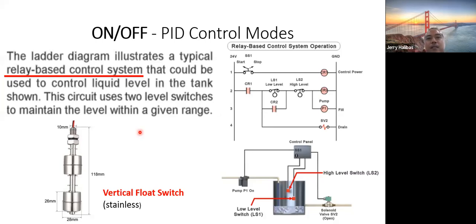The first difference is that electronics is faster. The relay system is much slower. But if speed is not the issue, if the issue is ambient temperature, then there is a problem in dealing with a purely electronic system. Your electronic system heats up easily if the ambient temperature is hot, so it is easily damaged.